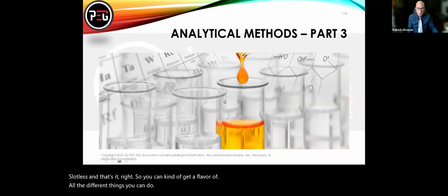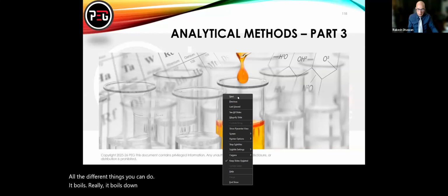It boils down to, if I look at the most useful architectures, I would say it would be the IPM designs and the surface mount magnet designs, right? Those are the two flavors essentially we play with. Surface mount magnet design is simpler to use, and with IPM design they want to exploit perhaps more torque density, etc., in being able to have a smaller motor design. But it does have a complexity in controls we'll discuss in the upcoming slides.